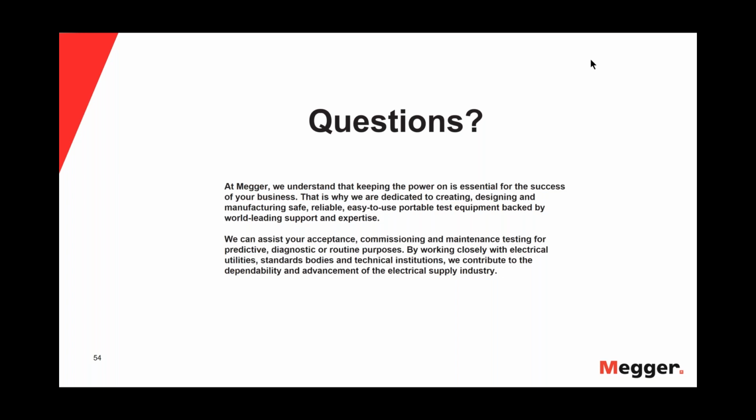I would mention that if someone uses this technique a lot for their particular infrastructure, there is another type of device out there. It's loosely called a thyratron, where it's basically a pulsing current set, and it can provide an excellent method for current chasing. Those are typically not off-the-shelf items, but if you're doing a lot of current chasing, we'd be happy to have a conversation with you about equipment that is fine-tuned, if you will, for that method.